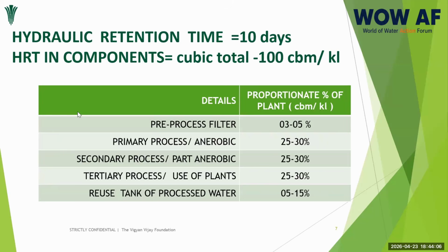We use a 1:100 flow gradient. And at times, whenever you have thick sewage or any pulpy matter coming out, we use a 1:50 gradient. Otherwise, 1:100 is okay. And it is all done on upflow.